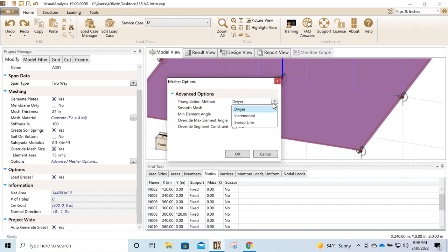And in the end, I would be refining my mesh until it got to some level of convergence. I was comfortable with the idea that what I had modeled was accurate to my interpretation of the real world, and on top of that, those things aren't going to change drastically if I continue to refine my model, to the point where I'm under-designing or over-designing something, right? Like a footing or a beam or a column.